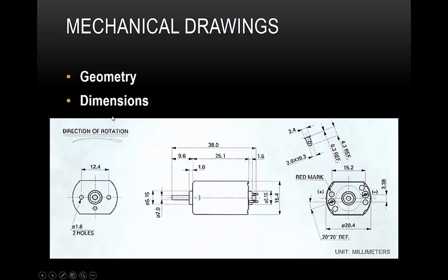Our dimensions represent the information necessary to recreate all of the features here, right? So here we have a little electric motor and all the dimensions that we would need to remodel this motor, to manufacture this motor, or to build around this motor. So it's very important that these dimensions are correct and that they're clear, because the machinist or the manufacturing company is going to have to build what you specify, and they have to know exactly what it is, right? And you'll notice that there's a lot of numbers here and there's a lot of arrows and stuff like that. Somewhere on here, either these units themselves will have the millimeters mark, it'll be mm, or somewhere on the sheet it'll say millimeters. So we know that all the units here are in millimeters or in degrees and stuff like that.